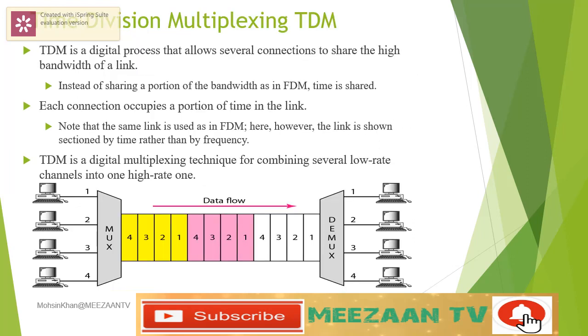Time division multiplexing (TDM) is a digital process that allows several connections to share the high bandwidth of a link. In TDM, time is shared. Each connection occupies a portion of time in the link. Note that the same link is used as in FDM. Here, however, the link is shown sectioned by time rather than by frequency. In the figure, portions of signals 1, 2, 3, and 4 occupy the link sequentially. TDM is a digital multiplexing technique for combining several low-rate channels into one high-rate one.